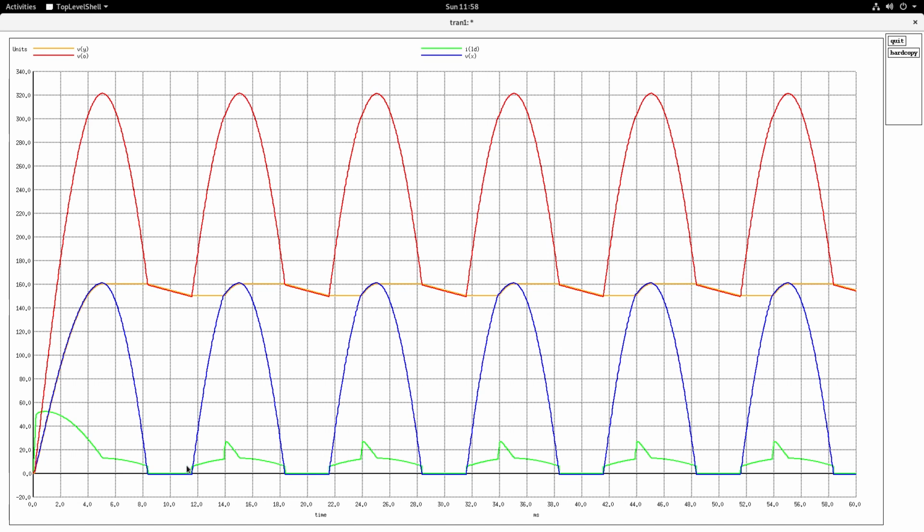The basic takeaway is that we have introduced a current wave shape with a larger conduction angle, thereby reducing significantly the peak current and improving the power factor. But all this is at the expense of an output voltage ripple which is very high.